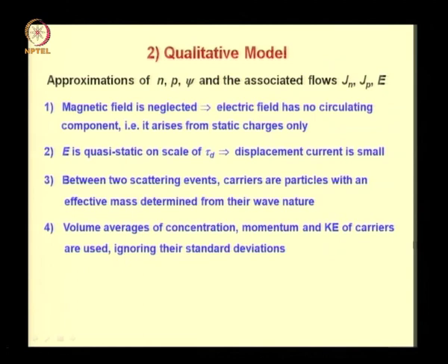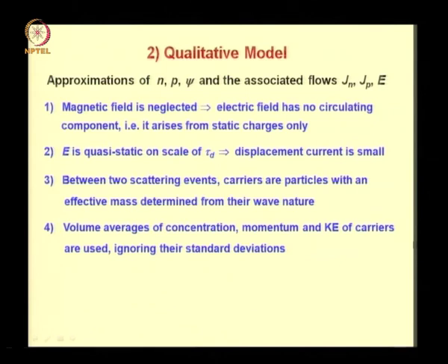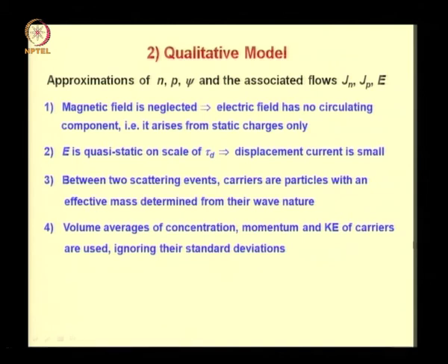The dopants are randomly distributed, and therefore the electrons and holes are also randomly distributed. Therefore, if you take a volume, let us say 1 micron cube in a device of 1 centimeter cube volume, and we look at different 1 micron cube volumes in the device, these different 1 micron cube volumes will have different concentrations of electrons and holes and dopants, even if we assume that the doping is uniform. For more on this, please review the discussion in module number 2.